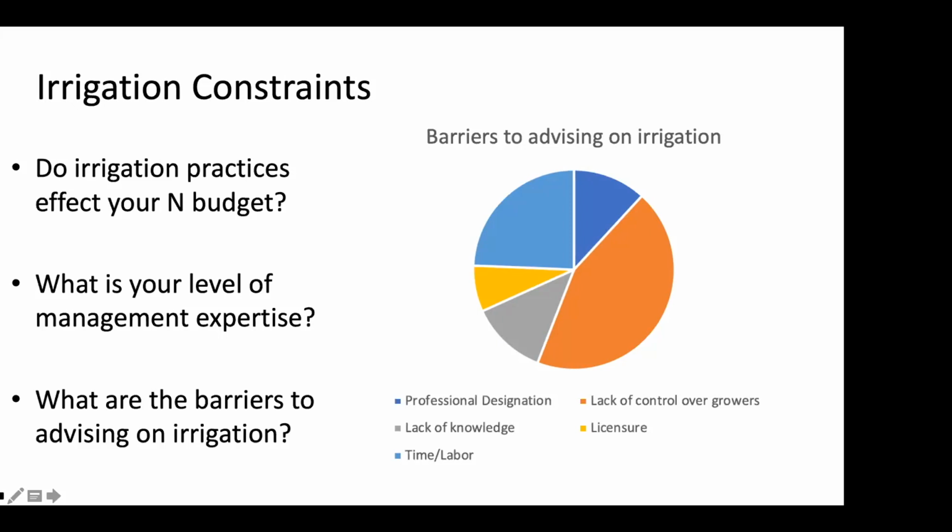And what are some good practices around irrigation, talking about distribution uniformity, for example, or scheduling irrigation with ET, but also soil moisture sensors, so you know at what depth your wetting front is moving to. Bringing that awareness to growers is really critical. But all those don't happen by themselves. They have to happen in unison. So that's going to require more investment, and that investment is probably going to have to come from the public sector. If we as a public want to see water used more efficiently, and we're interested in water quality, then we need to invest in the ability to do so.